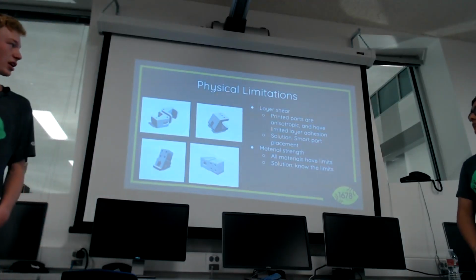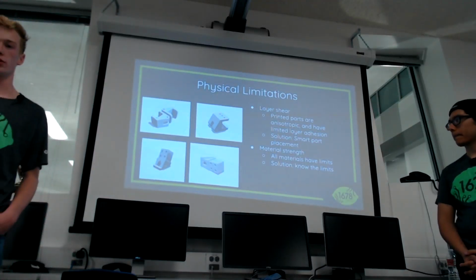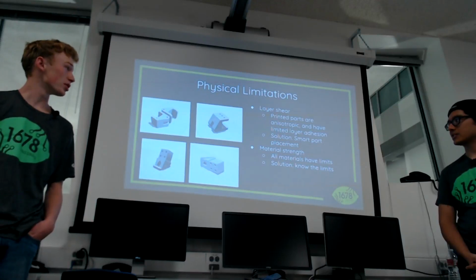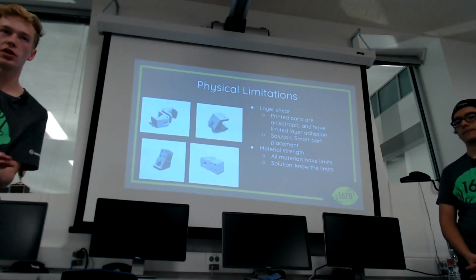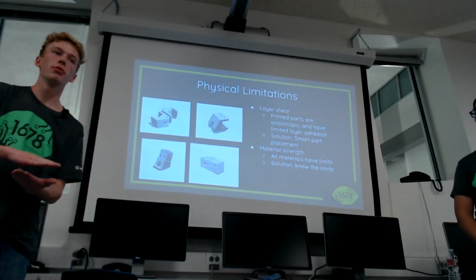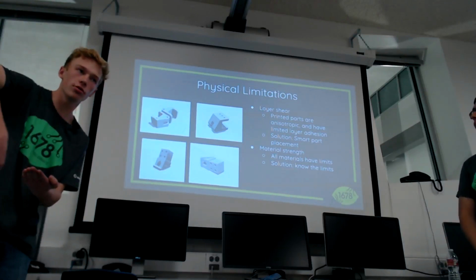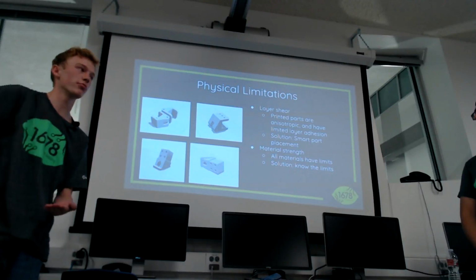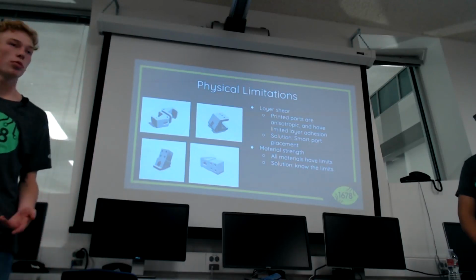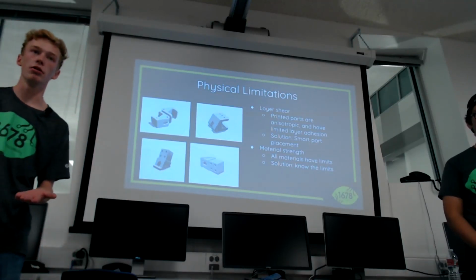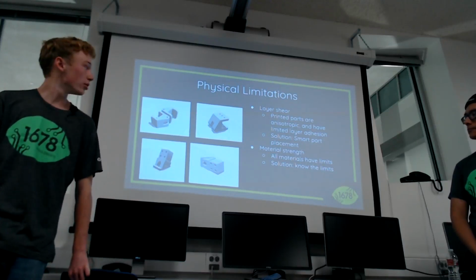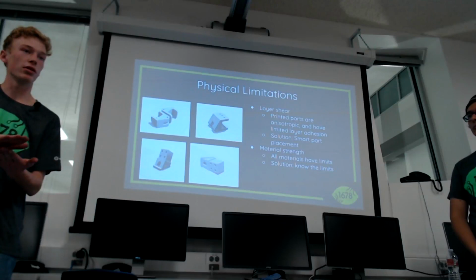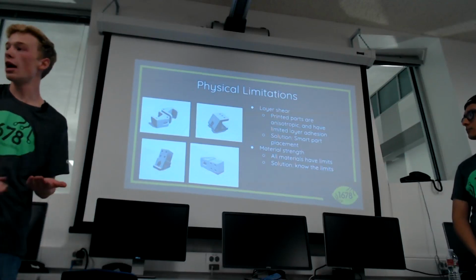So definitely, this next point is the most important one when it comes to limitations of 3D prints, and this is layer adhesion. The idea is that as a printer is printing along, within a single layer, it can make that layer super strong. It can extrude a single strand and have all these crisscrossing patterns and everything. But between layers, it's limited on just how well it can get each layer to stick on top of the one before it. This can cause a bunch of problems because the area in between the layers is always going to be weaker in shear than anywhere else in the part.